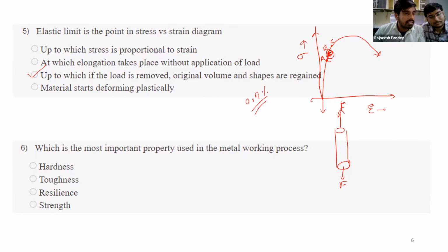First plastic deformation will always occur at the yield point. If you want to correlate with the elastic limit, you should cross the elastic limit to get any amount of plastic deformation. That's why we take this 0.2% strain, so we can get some evidence of plastic deformation in the material.